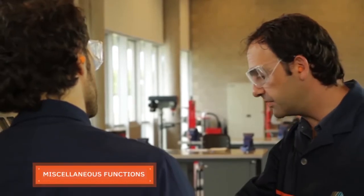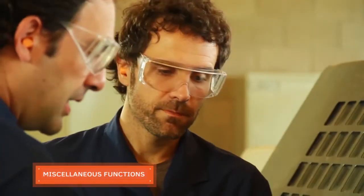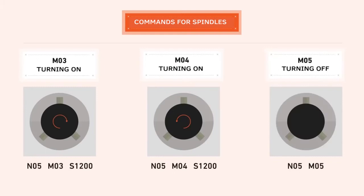Joaquin, let's look a little bit at miscellaneous functions. Okay. Let's see. If we want to turn the spindle in a clockwise or counterclockwise direction, we have the M03 function, which allows us to turn it clockwise. And we have the M04 function that allows us to turn it counterclockwise. And then if we want to stop it, we have M05.